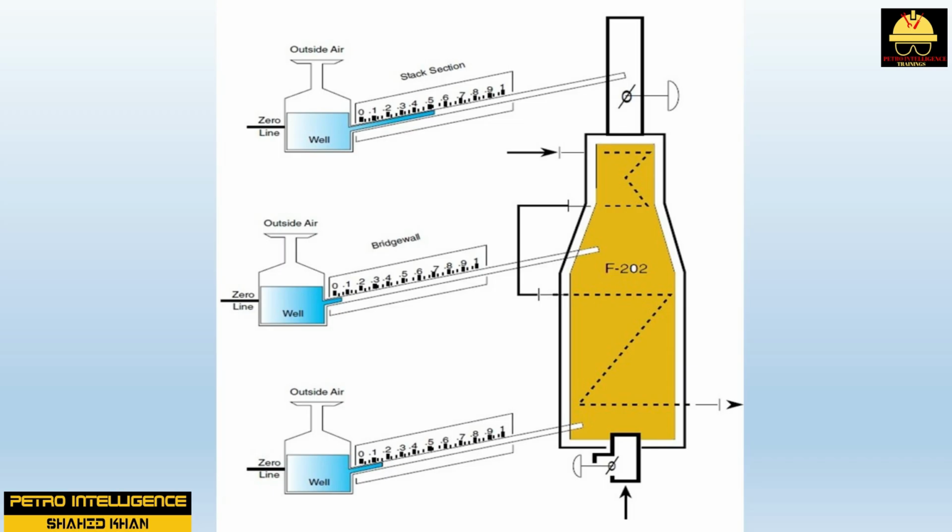Higher temperatures are found in the upper section of the firebox due to the reduced heat transfer in the lower section of the firebox. Temperatures in the convection section and stack will also rise significantly. This will reduce the amount of heat available for heating the hot oil, and more fuel will be burned in order to maintain process specifications.